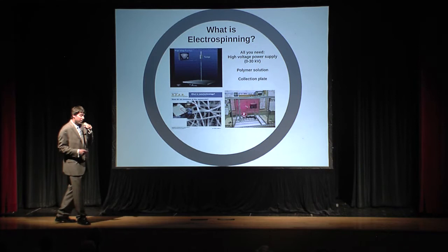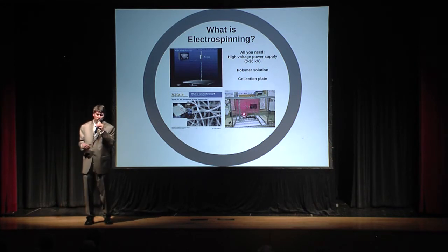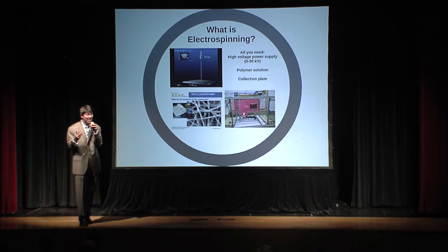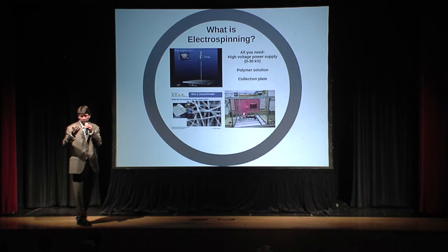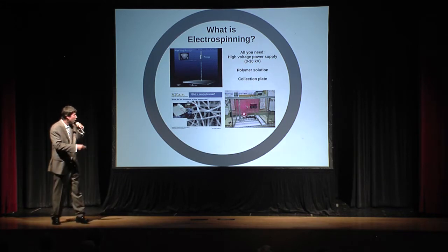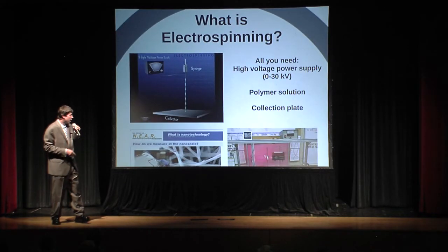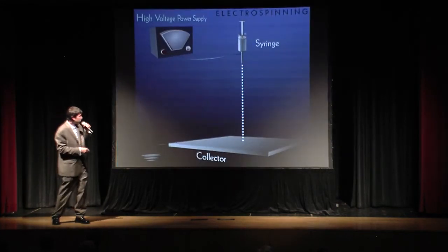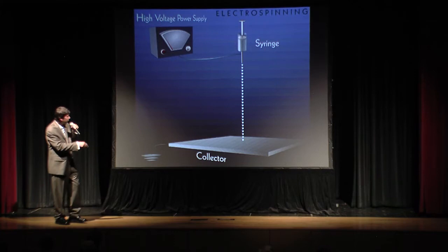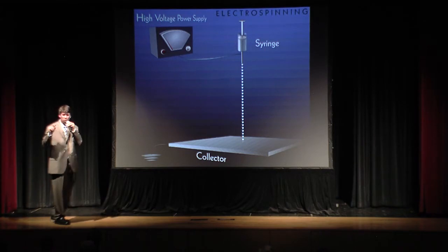Now the last thing is, how do I introduce nanotechnology to the students? How are they working? How are they functionalizing materials? How are they making them smaller so that we can actually do something with them? One of the things I learned with Dr. Koh and all of the research that he does at Drexel was a process called electrospinning. To electrospin, you need 3 things: a high voltage power supply, a syringe, and a collection plate. This syringe is filled with a polymer, a liquid polymer.